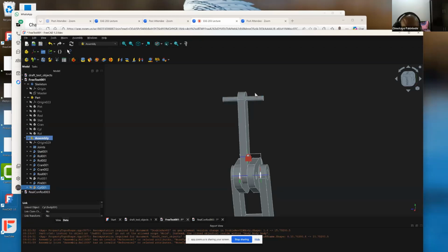The motions are more reliable when the physical object is there, even though the motion is abstract. Once you set the places that are supposed to be in the joint, the motion will be made, but it is not reliable. So when there's a motion, try and put the physical object, because that's how FreeCAD works. FreeCAD is more reliable when the physical object that connects this one to the piston exists.